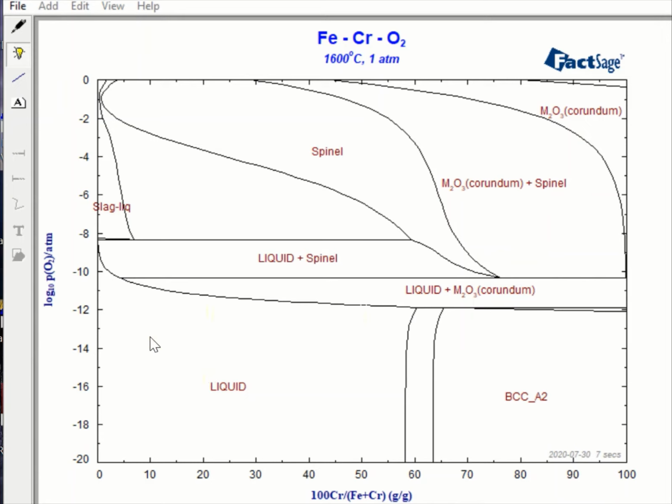So this is the very simple diagram, metal content versus partial pressure of oxygen. Of course, you can do the similar thing, metal content versus partial pressure of S2, SO2, and whatever gas species you can use here too. And you can also do multi-component phase diagram calculation like this. So you can set a multi-component system with a certain fixed actual composition, iron, chromium, aluminum, nickel, and etc. All the rest of them is the fixed value, and only changing the chromium amount. Then you can use it in this way, and then do the same calculation.